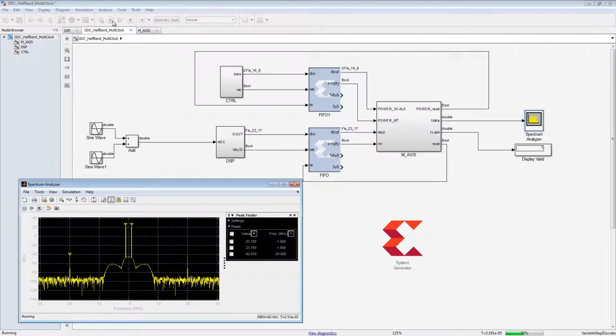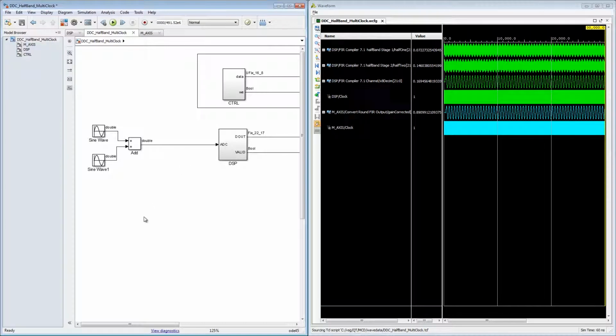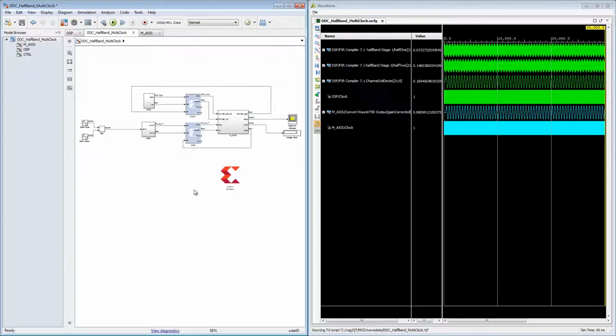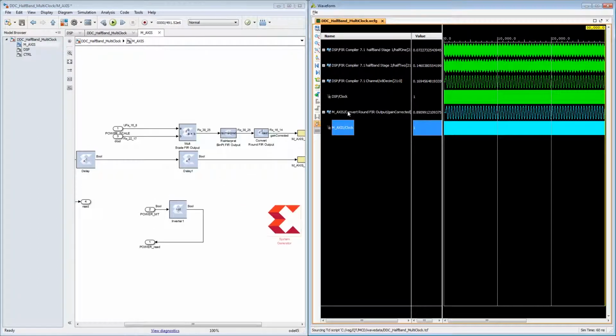Each clock domain in the waveform viewer is denoted by color. Selecting the clock in the waveform cross-probes into each domain, and this also enables cross-probing with each signal. For more information, please see the Xilinx View Signal chapter in User Guide 897, Model-Based DSP Design Using System Generator.